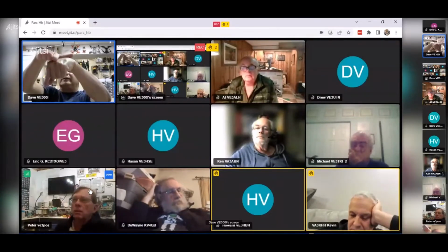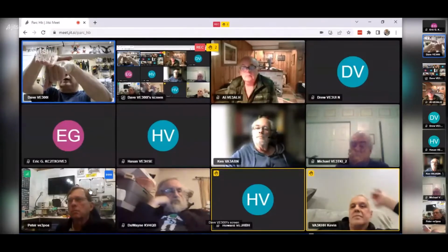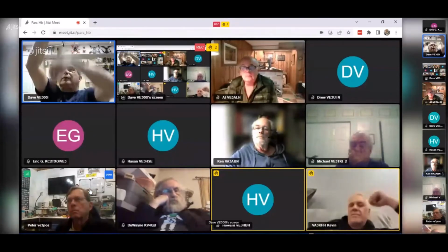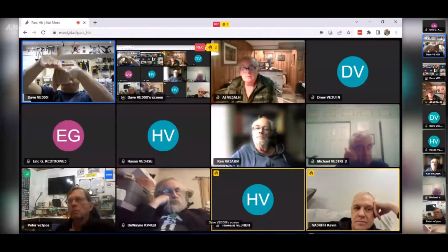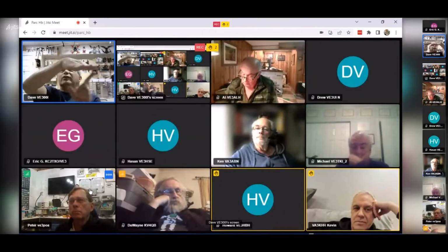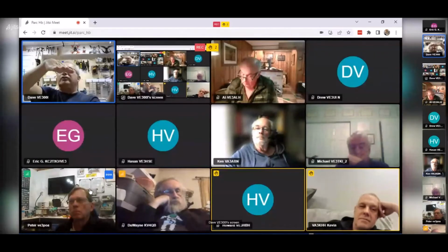But if you take this board and you move it up, that's a real acceleration, and that 1G now may go to 0, or it may go to plus 3Gs. Or if you move it this way, all of a sudden there's a real acceleration in this direction, and so your accelerometer, this axis, is going to give you an acceleration value.